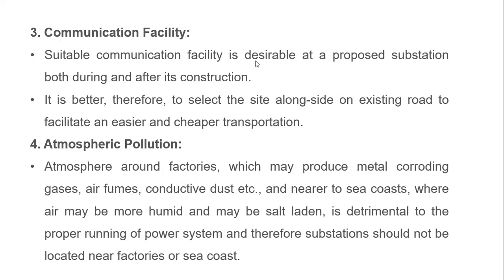Suitable communication facility is desirable at a proposed substation, both during and after its construction. After the construction and also during the construction we require suitable communication facilities. It is therefore better to select the site alongside an existing road, for easier and cheaper transportation. Whether it is near to the load centers or not, that will all be checked.